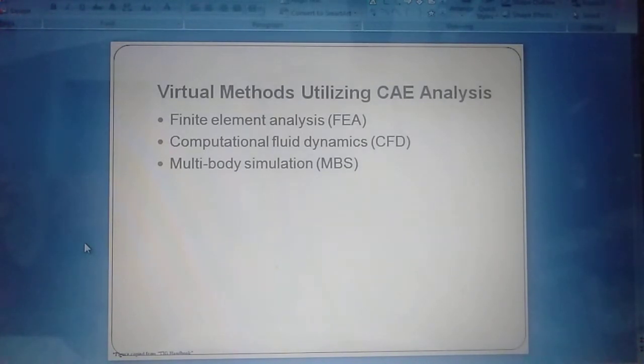The separation of the locally distributed parameters into discrete parameters, for example mass, inertia, stiffness, damping, leads to the physical discretization of the product model. Besides the rigid consideration of kinematic systems, elastic sub-bodies from FEM modeling can be imported and integrated on demand.